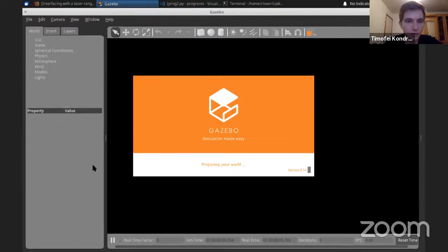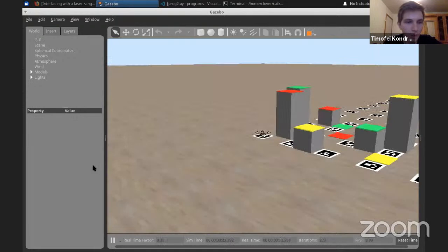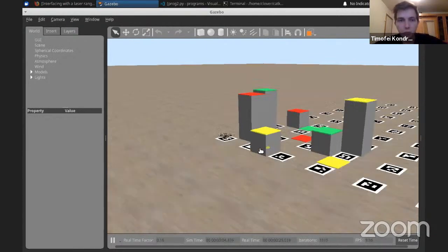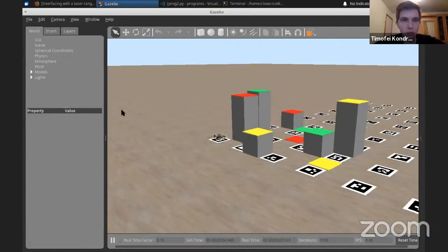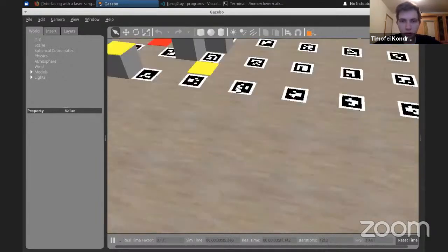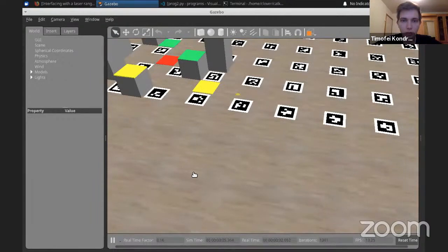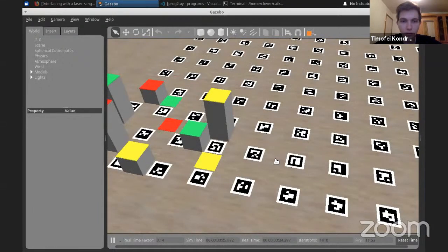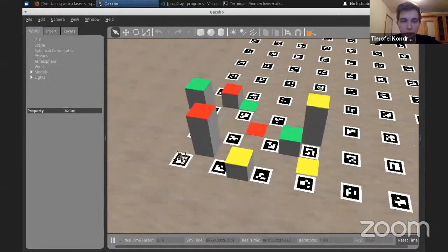So there is a question: what happens if I use different ArUco markers or in different order? Well, in order for the markers to work properly, you need to have the same setup in your physical markers location and your marker map that is stored in the drone's memory in a TXT file. If they are different, then some problems may occur.